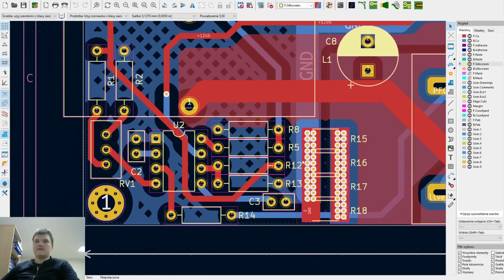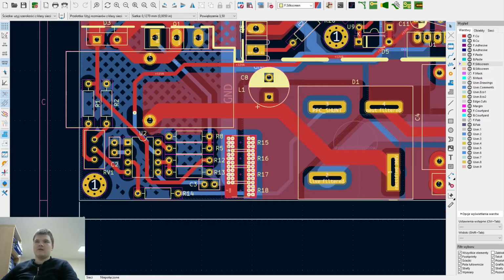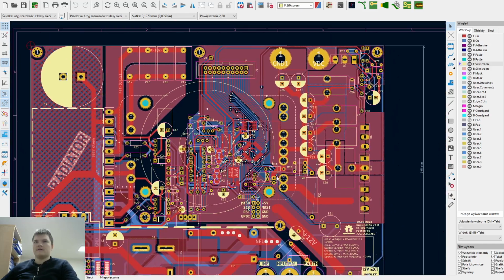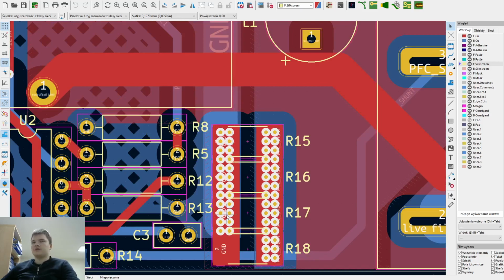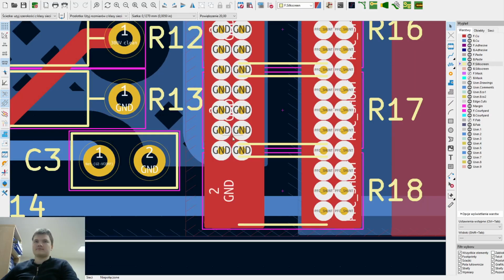Here's the PFC. Here's the shunt for the high voltage, not the low voltage, because there's such immense current that will be going through the low voltage side that it would take an awful lot of surface mount resistors or maybe even through hole ones to do this, so that's not possible. There will be an external shunt that will allow me to control the current passage.